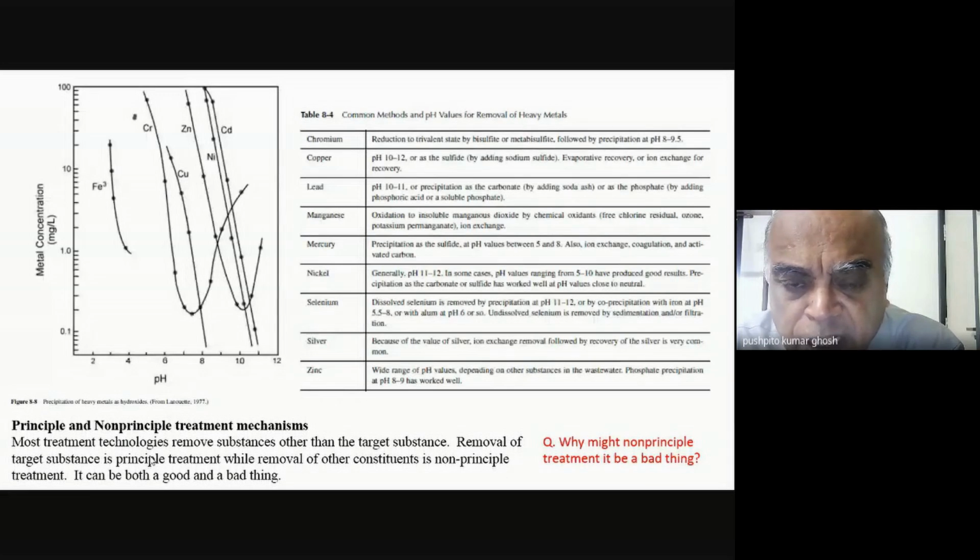Otherwise I will not allow you to discharge your effluent. And otherwise everything else in your effluent might be okay. Maybe the BOD, COD, those kinds of things are okay, but it's these heavy metals which might be coming in the way. And then you may say, chromium, it should be possible to separate it out by precipitation, at least much of it, not all of it.